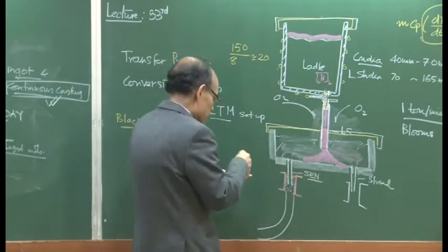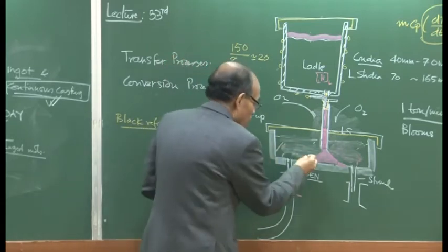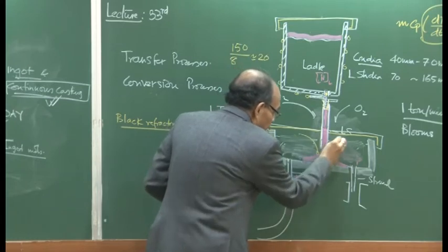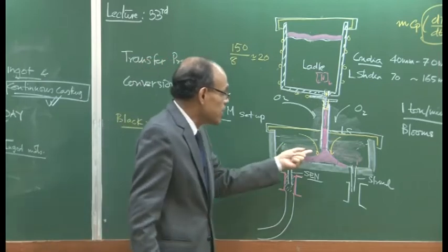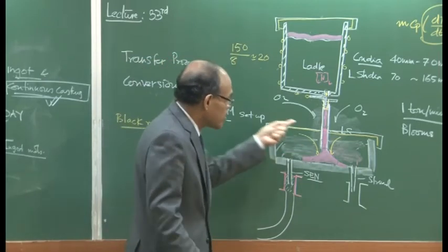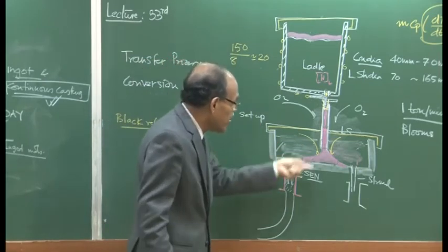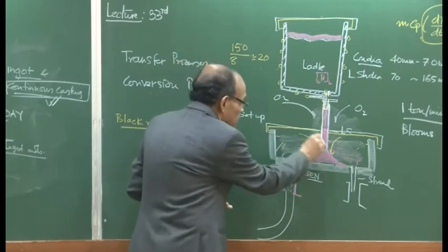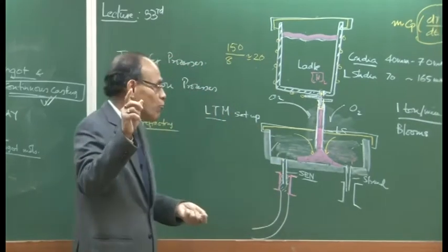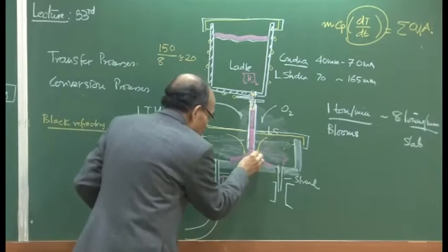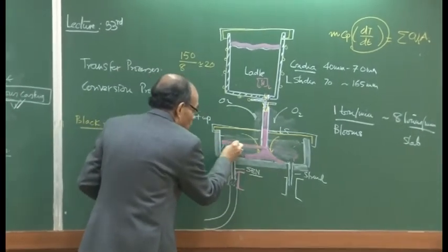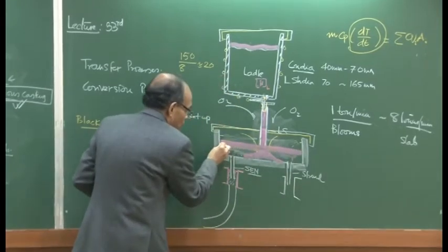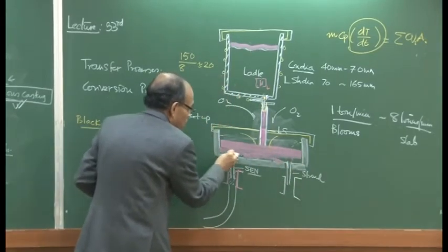Therefore a huge amount of atmospheric air will get into the tundish, as a result of which molten steel is continuously dissolving and entraining oxygen from the tundish environment. This phenomenon will go on till the shroud tip is submerged, and then of course there is no more oxygen entrainment.